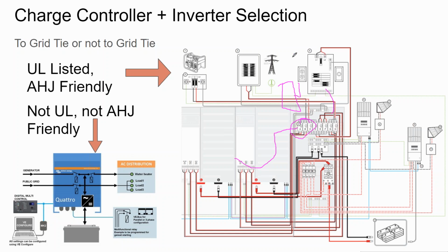The reason I don't like these knife switch disconnects, and the reason they're not part of National Electric Code, and why many jurisdictions have moved away from requiring them, is because you've got the grid coming in on top and the load coming from the bottom. You switch this disconnect off, and it still doesn't kill the grid coming in from the top.